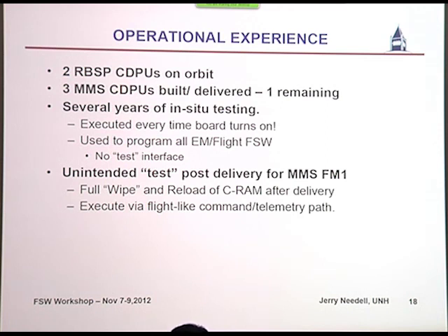You said there was, I'm not sure which, RBSP, but the MAC data had to be provided to the spacecraft even while in boot mode. Right. Doesn't that violate your idea of not accessing any hardware outside the FPGA? When I said the requirement was not to rely on memory resources, SRAM or CRAM, in other words, we don't want to make any assumption about what code we have available to us.